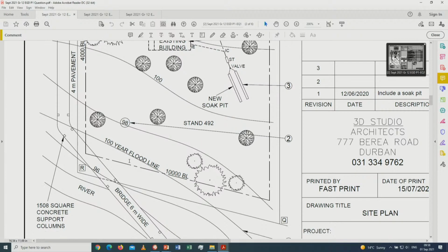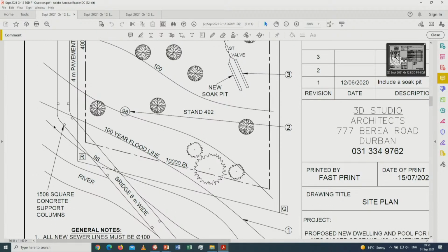All right, what I mean by this is by saying that your contour interval on this drawing over here is 96 meters to 98 meters. That gives you a difference of 2 meters. So this is in between. So that is the contour line in between. And the sequence, the contour lines are basically those ones that will be in 2 meter, 2 meter, 2 meter differences. So you can't expect the learner to make this as a contour line because it's not part of the sequence of 2, 4, 6, 8 and further onwards. So in this case, that line, although skew, although free-handed, is basically the flat line itself. All right, so that's what it points out.